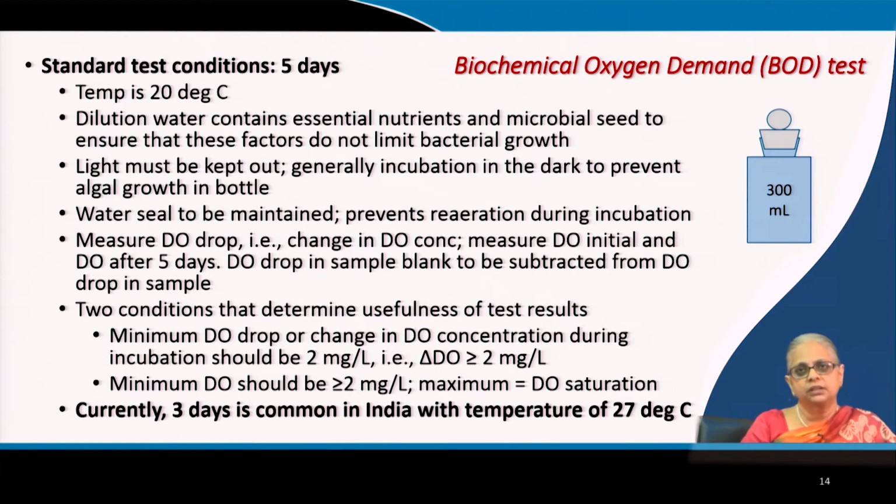So it's got an inverted top, and the stopper is also made of glass, but it's frosted glass. And when the bottle is filled to the brim, this glass stopper is literally dropped into the bottle to create what is called a water seal. Now this water seal will prevent any re-aeration during the incubation period.